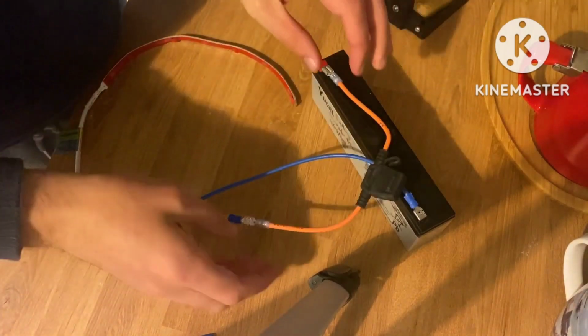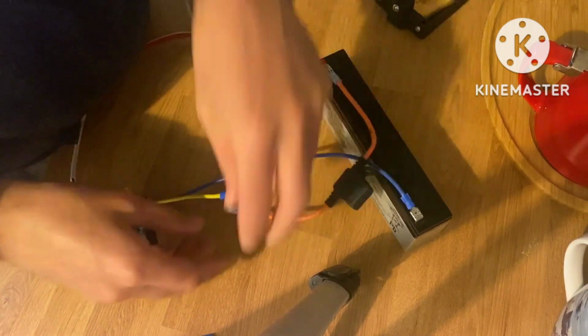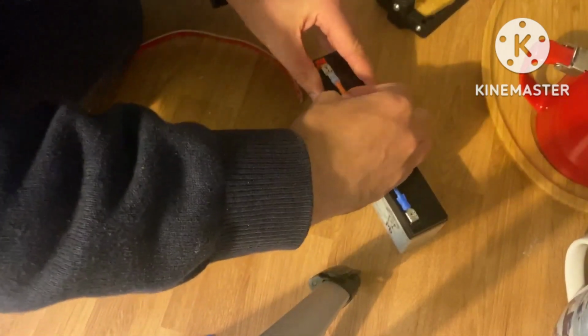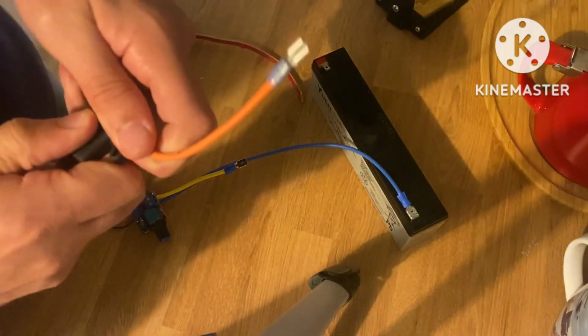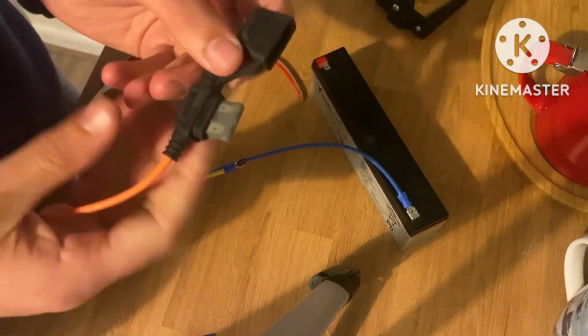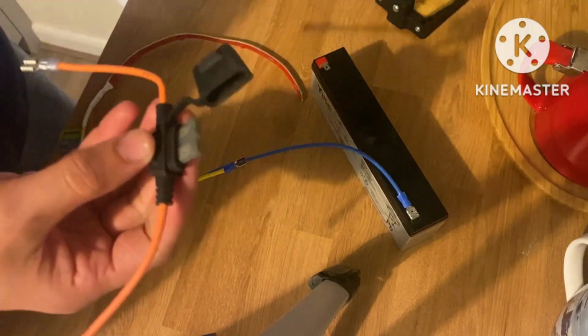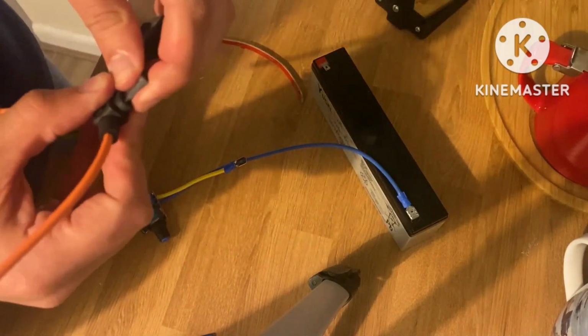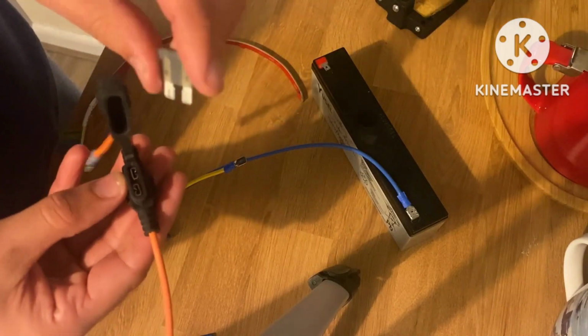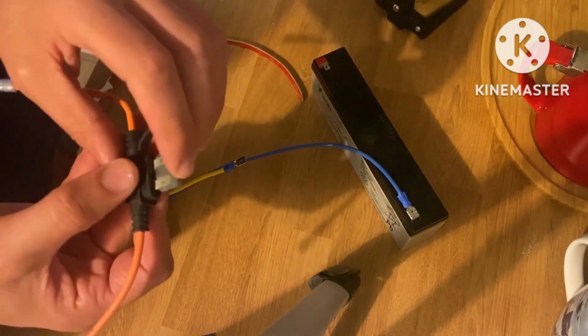One thing I should say before I forget is don't forget to add a fuse. The amount of times I've seen people not add fuses into circuits, it's very silly. I had one person once tell me, oh, I don't use a fuse because they always blow and then it stops working. You're sort of missing the point. The point of a fuse is to break under certain conditions. It's what we call a sacrificial component.